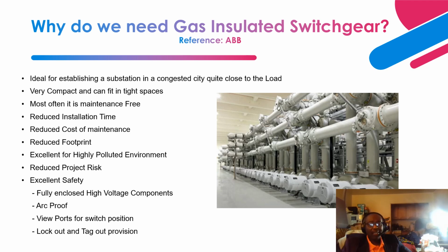Because it is enclosed in a metal enclosure, all the components are enclosed, so it basically becomes the ideal candidate for a highly polluted environment. Next is reduced project risk. I made mention that installation time is reduced, right? As such, it reduces the risk associated with projects, and a lot of that risk is delays in meeting due dates and closeout dates, right? Because they come already assembled in the factory, installation time is much faster.